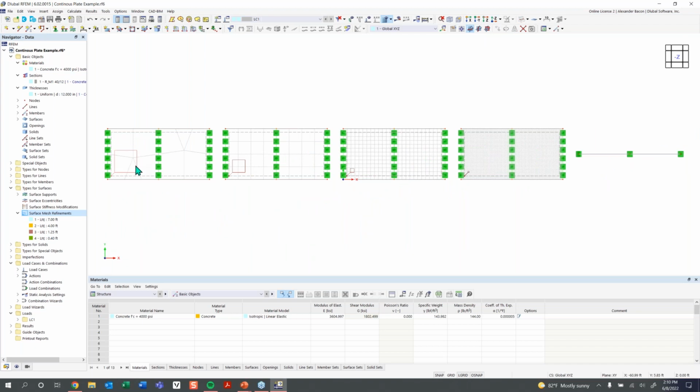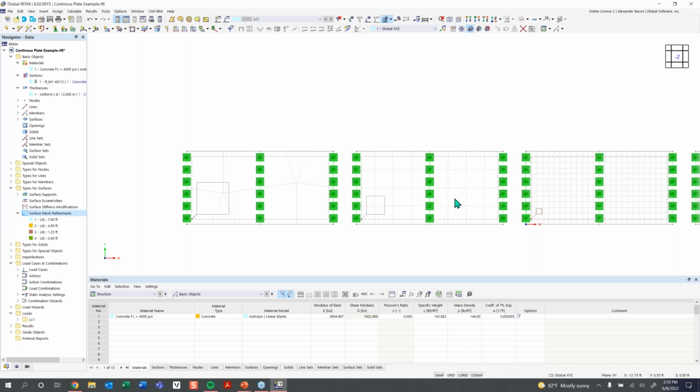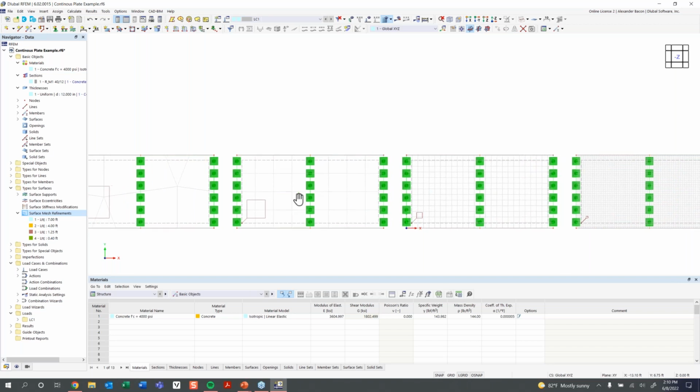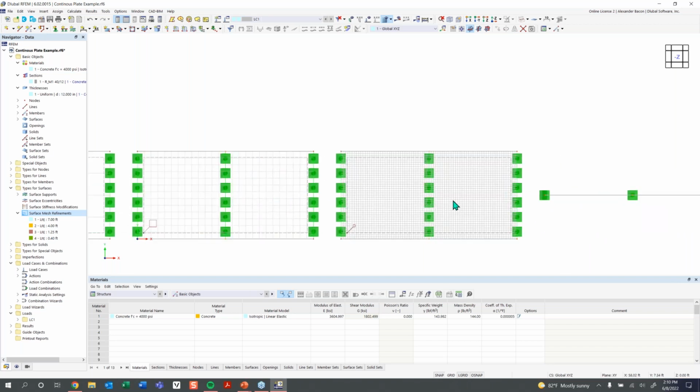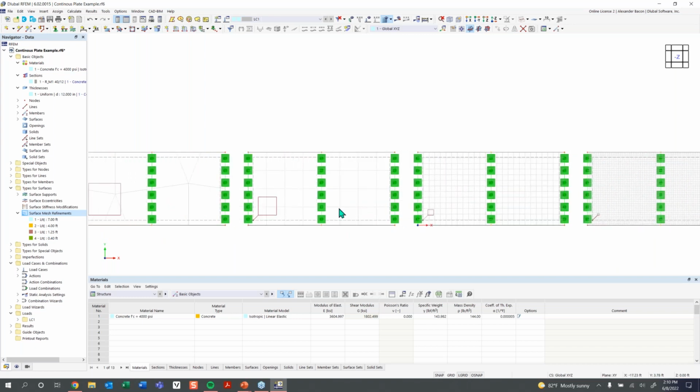So you can see gradually as we move from left to right here, our FE mesh starts out pretty wonky. And then the smaller the finite element gets, the finer our mesh gets and starts to look a lot better. So this is as we, from left to right, decrease the size.